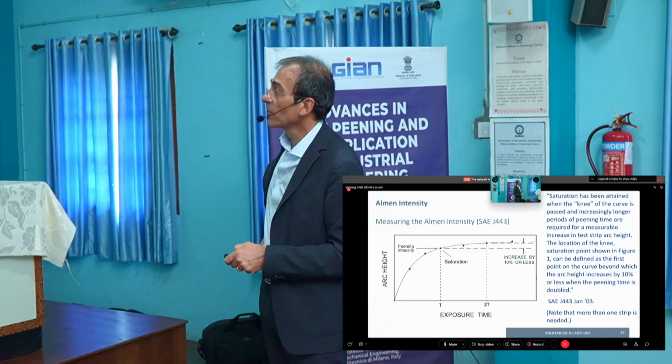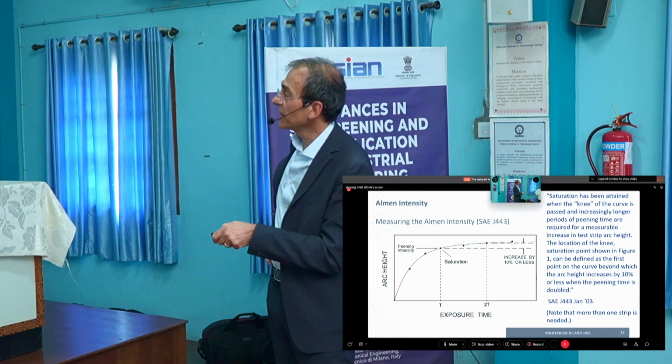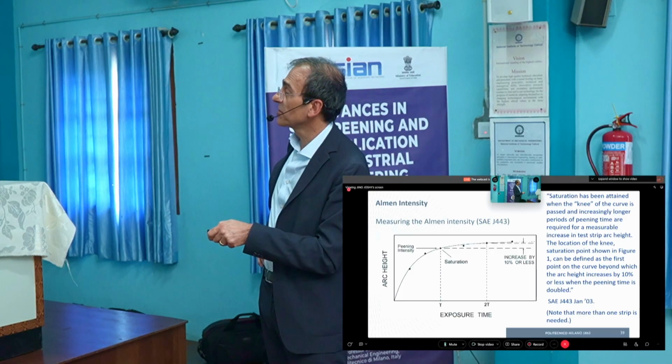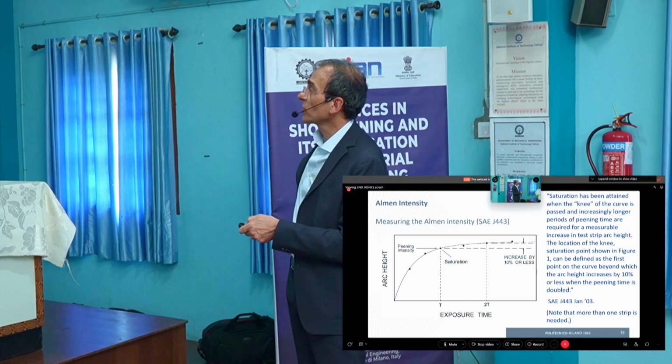Or in other words, this is a more quantitative evaluation: when we double the time with respect to this, and the increment is less than 10%, this means that we have saturated the ability of the strip for plastic deformation.